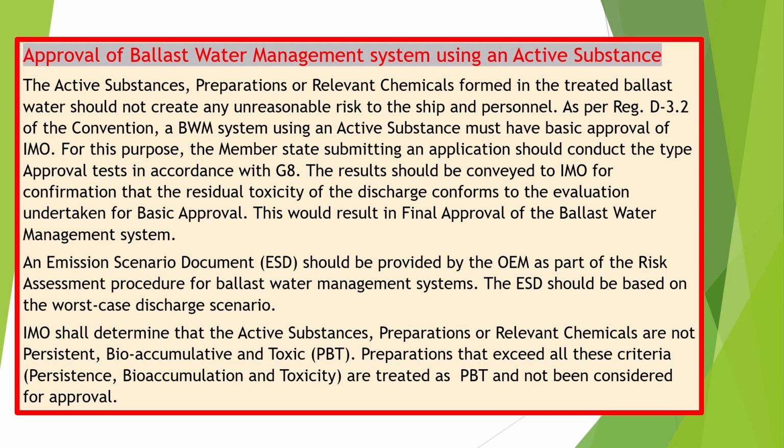Approval of ballast water management system using an active substance. The active substances, preparations, or relevant chemicals formed in the treated ballast water should not create any unreasonable risk to the ship and personnel. As per Reg D-3.2 of the Convention, a BWM system using an active substance must have basic approval of IMO.